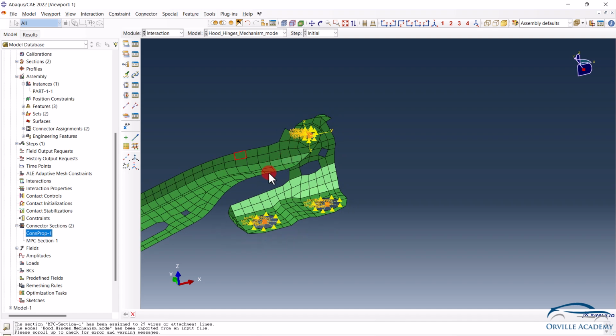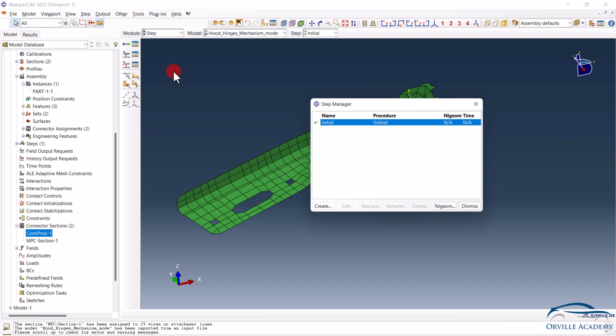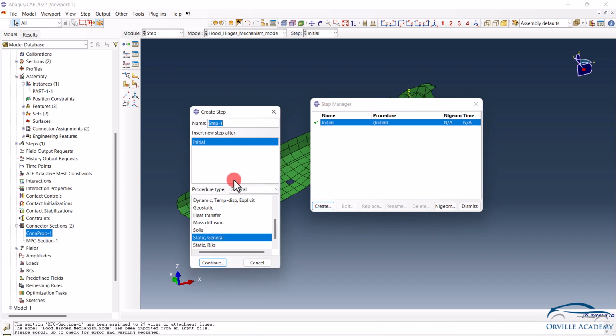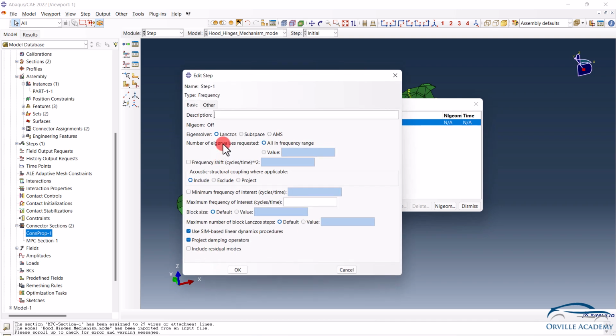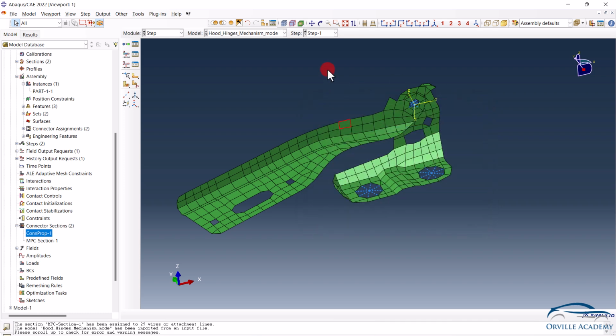Make sure whenever you get an orphan mesh file, you go through that file entirely so that there won't be any surprises for you. Now let us prepare the simple modal analysis deck. Let us go for the step, click on the step manager and let us go for create. Under the frequency, let us put the Lanczos solver and under the values, let us put 10. Simply click on OK button. For the output, let us keep the default output only and close it.